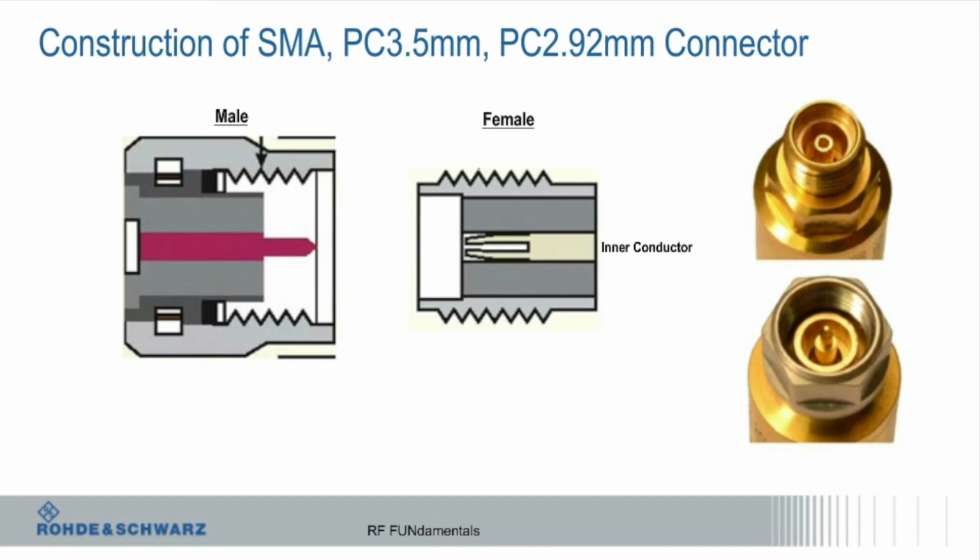That's the simulated threading of a connector. If you look at what's going on inside here, that's the female connector, and this goes over this when you thread it in, and you'll see in the next picture how it's supposed to look. One key thing to remember when you connect these: if you're using an SMA, I don't really care what you do. Well, no, that's not true. When you're connecting the male connector that has the nut that spins, that's the one you always turn. Don't turn the other one. That's how you'll degrade the outer conductor. For example, some of the better connectors are gold plated, so they have some thickness of gold on them. When you don't spin it correctly, you're going to scrape off some of that gold. So turn the nut, not the thing.